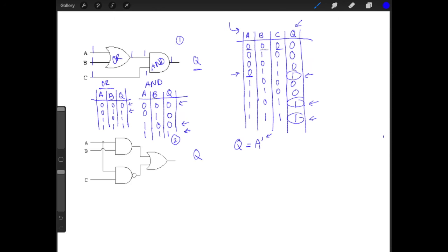So if A is inverted, and then B is 1 and C is 1, then it'll have an output of 1. So remember, this represents an AND expression. So remember, for an AND gate, the algebraic expression is like XY. It's basically kind of like multiplication, where the 2 inputs are next to each other.